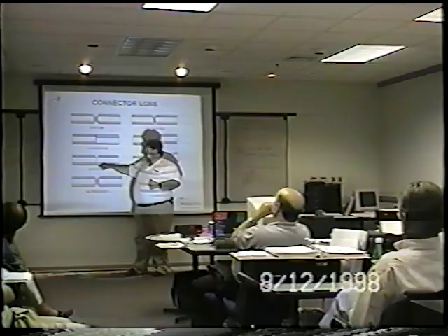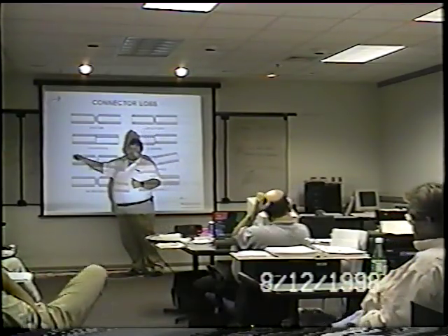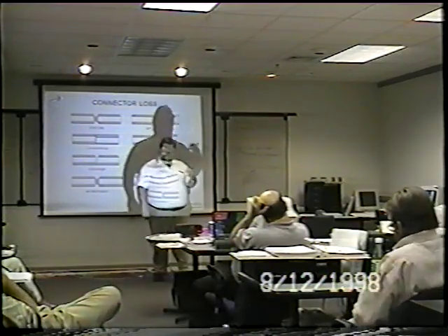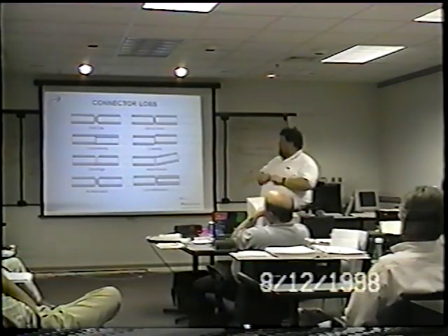So I mentioned earlier, if you get any kind of connector tip reflections at 1550, those reflections go back into the cavity and destabilize the laser. So in those cases where you have really hot optics, you might see some type of offset or an angle on the tip of the connector.